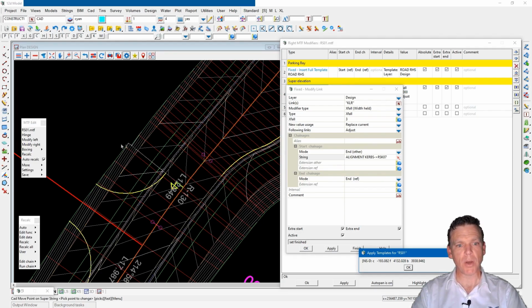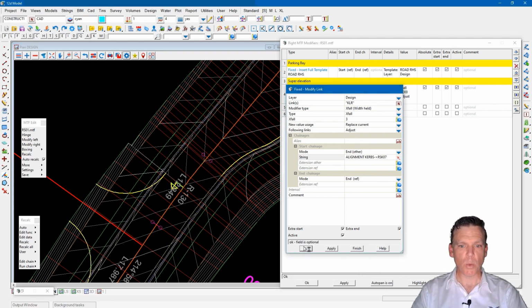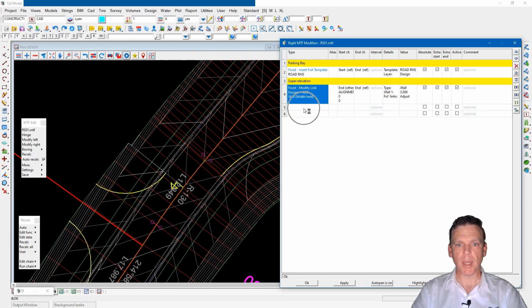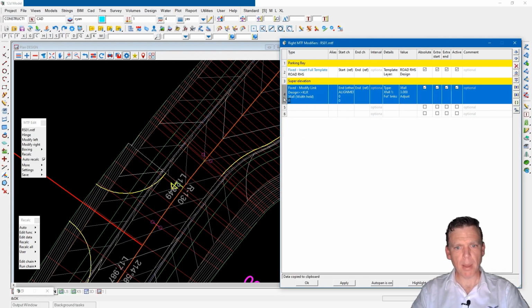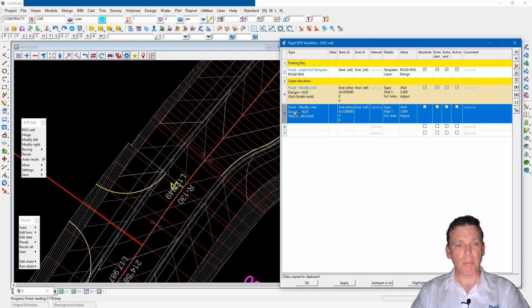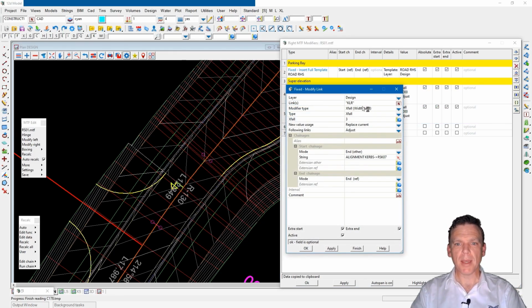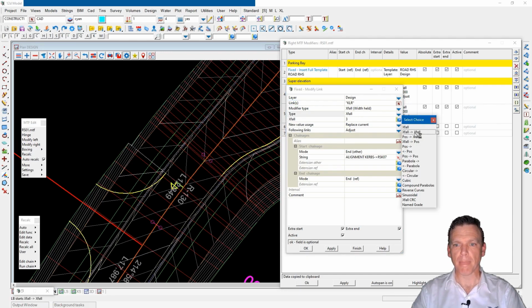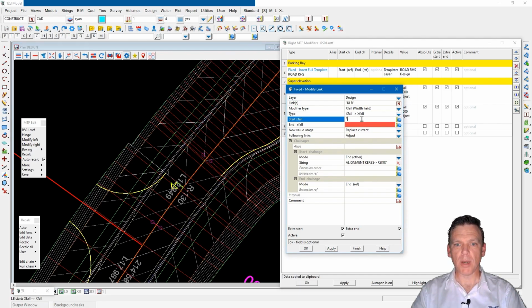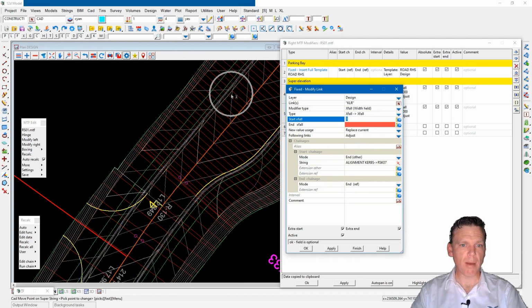It doesn't marry up very nicely because right at this very chainage here, we've basically just changed the crossfall. So that's working fine. We can then also put in a transition. So a bit like the height transition, sorry, the width transition we used before, it's the same string and I've just copied and pasted it down. I can change it so that I've got two crossfall answers. I could say I want to go from -3, which is what we have up the road here.